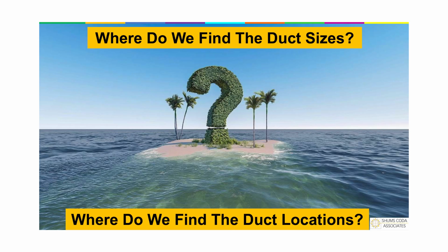What if they weren't on the plans? What other location or item might we find that information? Manual D, there we go. Yeah, a Manual D will give us at least information about where the ductwork is going to be located so we have a better idea, right? Because unless it happens to be a multifamily project where they actually provide us with ductwork plans, right? Like mechanical actual plans. Usually our only mechanical plans that we get is that Manual D.